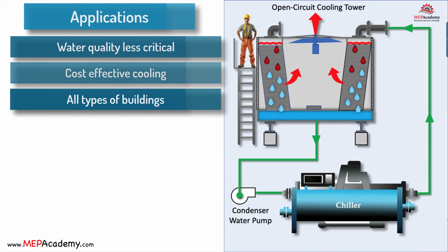The addition of a heat exchanger between the cooling tower and the chiller can add a layer of protection against the fouling of the chiller's condenser tubes, but at an added cost. This doesn't eliminate the need for water treatment of the tower, it just shifts the tower base of water from contacting the chiller's coil to the heat exchanger.